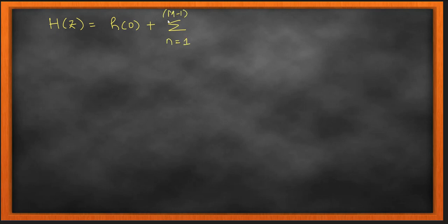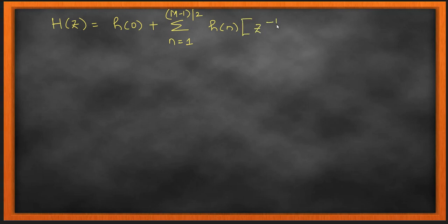We started with the Fourier series equation, and now we are moving towards adapting that equation to a complete full-fledged FIR filter. When I want to make that Fourier series formula into a full-fledged FIR filter, I have to make sure that it satisfies all the properties of the FIR filter.